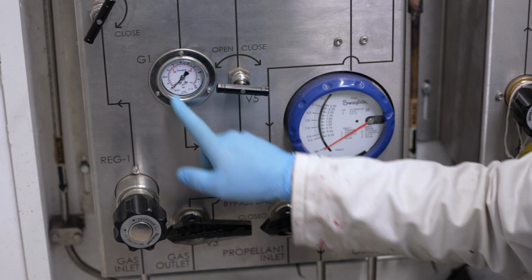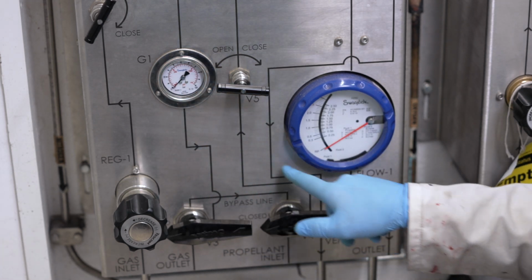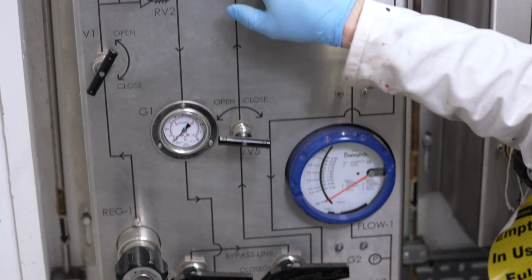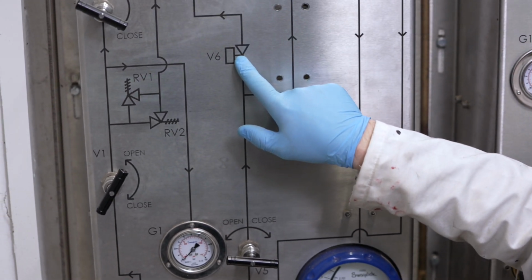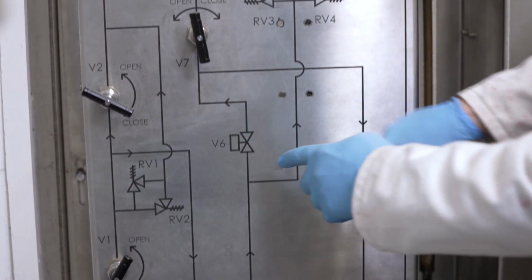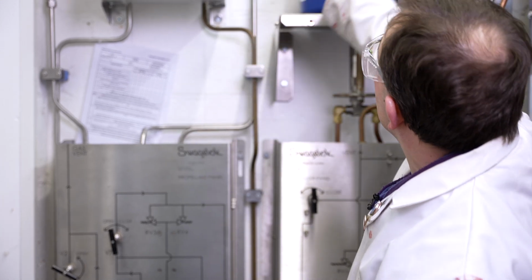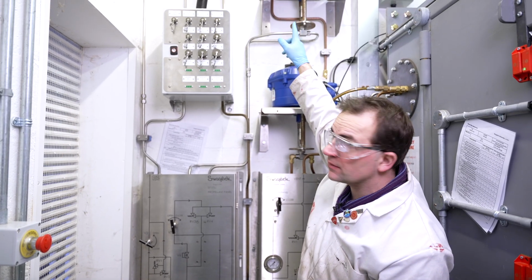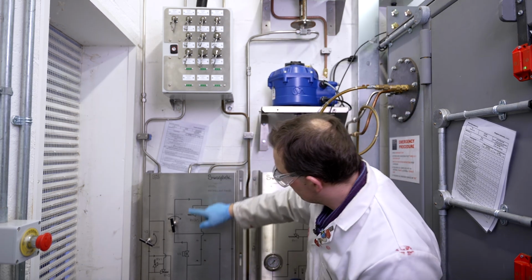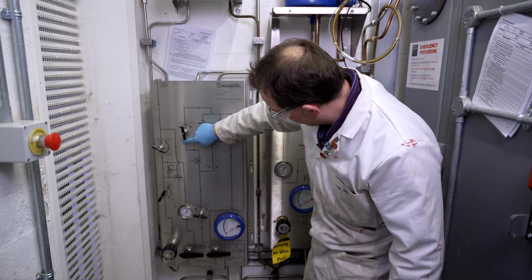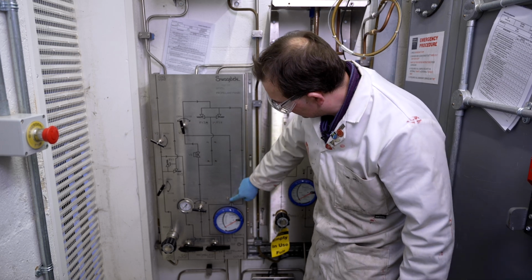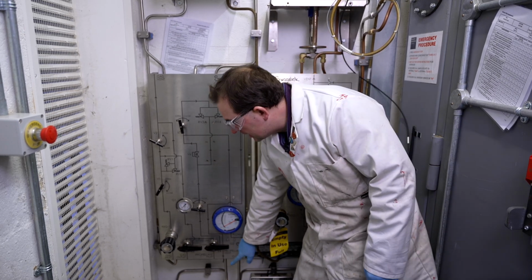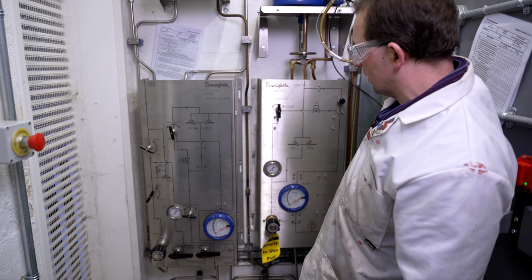But in normal operations, the gas would come through our gas lines, up through here, through our safety solenoid valve, which although it's here on the picture, is actually up here and is our Rotork safety valve. And then it will come back down into the system. It will flow through the pipe, through our flow sensors, and then off into the chamber.